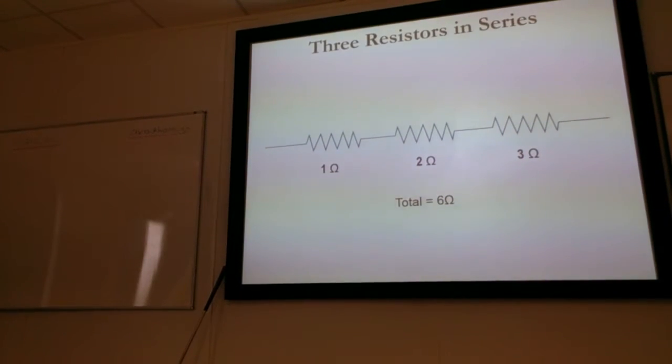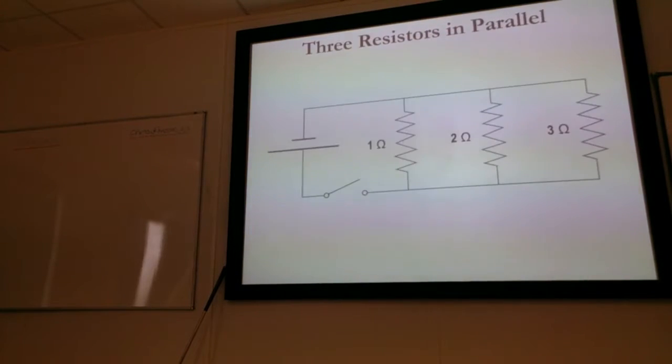Now there's a flaw with having resistance loads in series. We touched on it yesterday with our thermocouple, didn't we? We said that if we have them in series and one fails, we break the circuit. So you'll have nothing at all from that whole circuit. So your loads in an aircraft tend not to be wired in series, they tend to be wired in parallel. And when we wire them in parallel, some magic takes place. Those 3 resistors, a 1, a 2 and a 3, make 6 ohms in series. If we wire them in parallel, here's where the magic takes place.